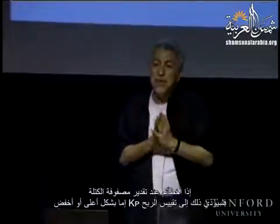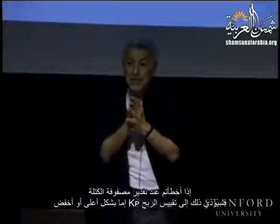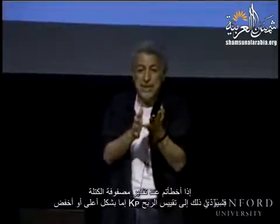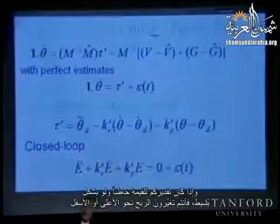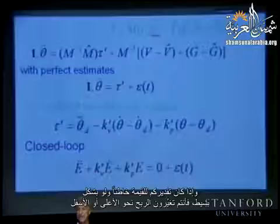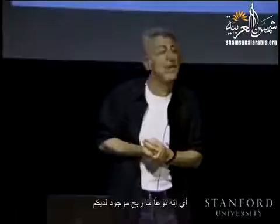Well, if you make a mistake in the estimate of the mass matrix, it's going to sort of scale up or down your gain, your Kp. So your Kp will be, with this structure, m hat times torque prime. m hat times torque prime means Kp prime is multiplied by m hat. And if that estimate is a little wrong, you are changing your gains up or down. So it is a sort of gain that you will have.